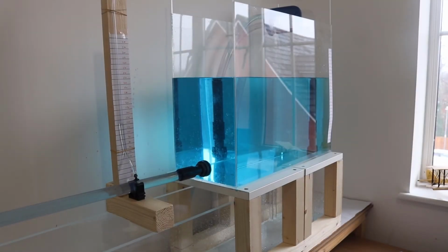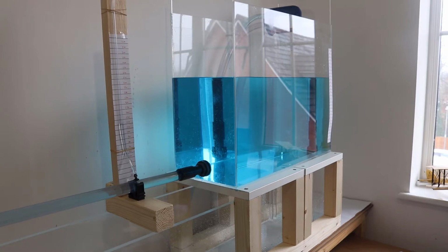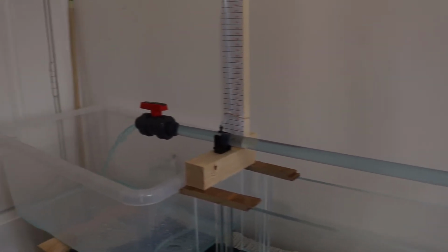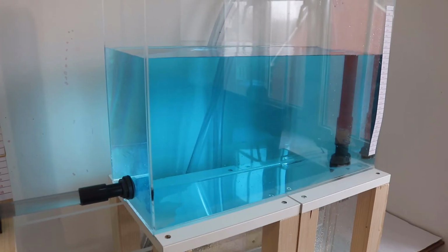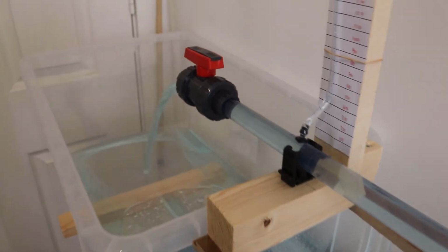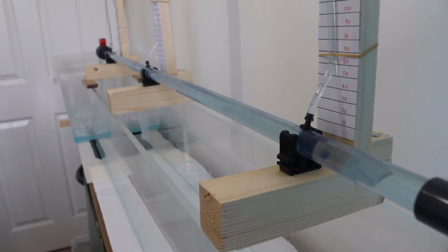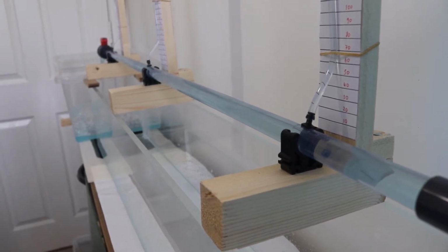So let's start with an example. Here I've got a constant head tank that has a water level of 209 millimeters. The system has a pipe that's 1.25 meters long and a valve on the end of that pipe. And we have three pressure tappings along the pipe, one just after the tank, one 0.5 meters further down the pipe, and another a further 0.5 meters along the pipe. So we can measure the system's pressure head in the supply tank and at 3 points along the pipe.